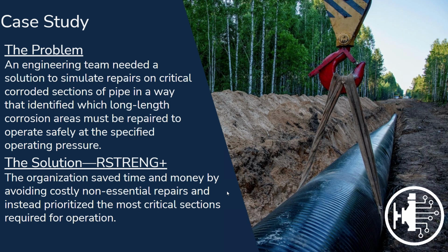And that's one of the big challenges. We have different methods, like a Type B steel sleeve, which becomes a pressure-retaining vessel. So if you did have cracking, that would be a perfect application. You could use your composite sleeves as appropriate, but keep in mind one of the things the regulators say is for a permanent repair. So do all these repair methods meet that definition? Keep that in mind. And this is one of the approaches we have to think about when we're coming to repairs.